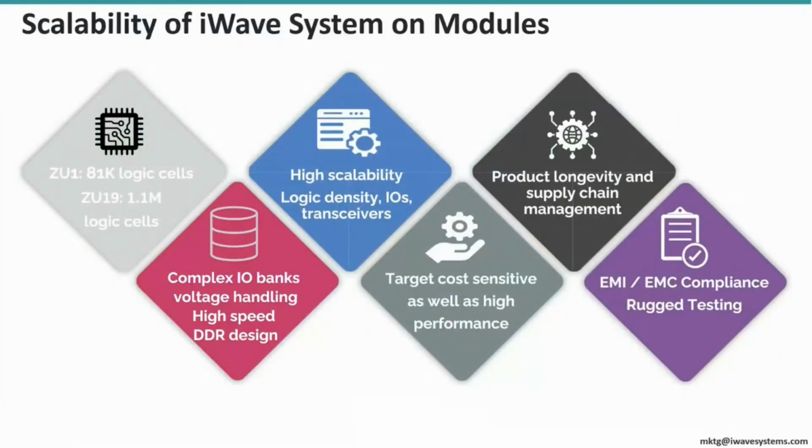Summarizing how it helps solve your challenges on medical product design, the MPSoC architecture in a system on module provides a scalability from the ZU1 with 81K logic cells to ZU19 with 1.1 million logic cells. So depending on the application, you have the complete scalability and options to choose one. The SOM also helps you solve complex design challenges such as the IO banks handling or the high-speed DDR memory design.